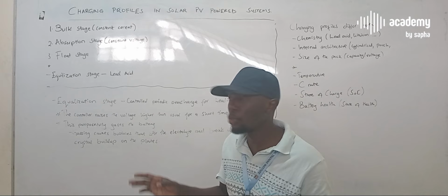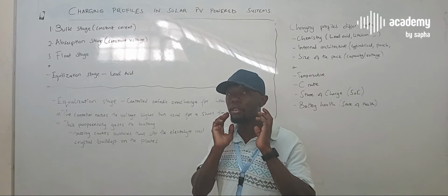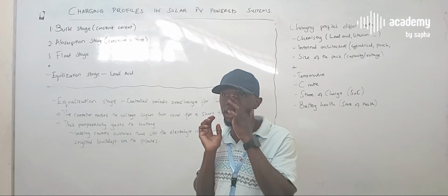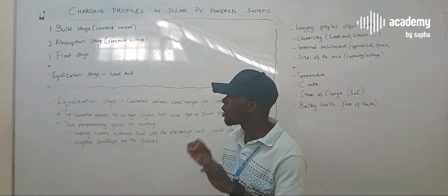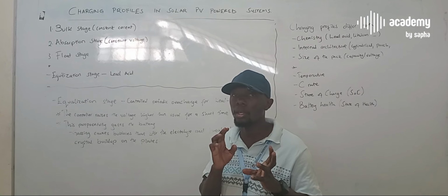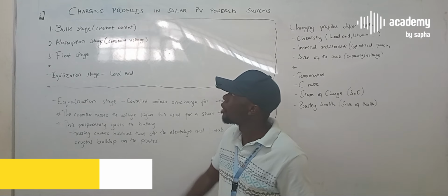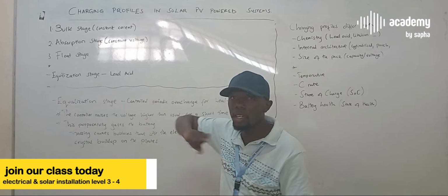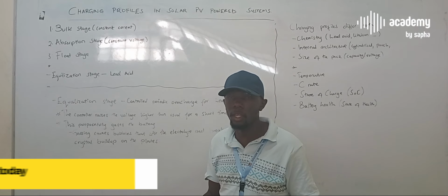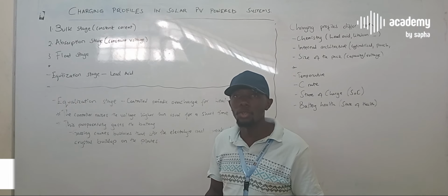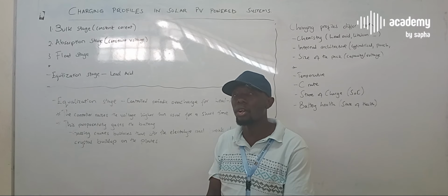So I hope up to there now, I think you now have a brief, I can say now, an established idea as to why the communication protocol is important. If a communication protocol between the battery and inverter is not well established, your charge controller will just be sending one category of voltage all throughout the battery's life cycle. So your charge controller could just be sending, like if you've linked it to a charge controller that can only